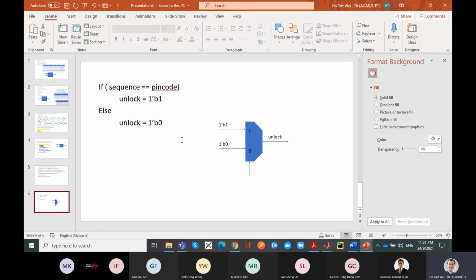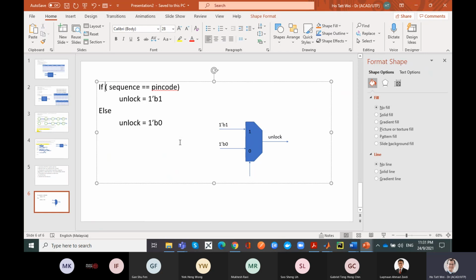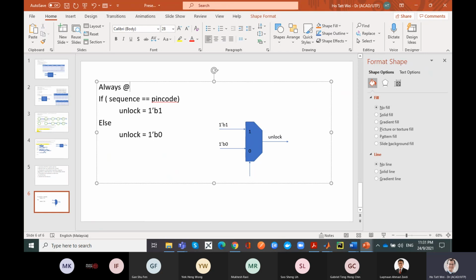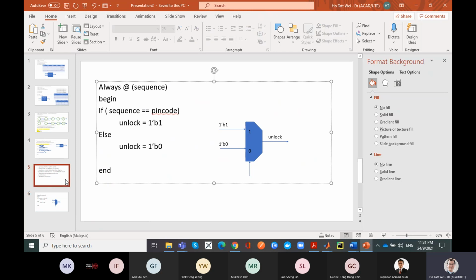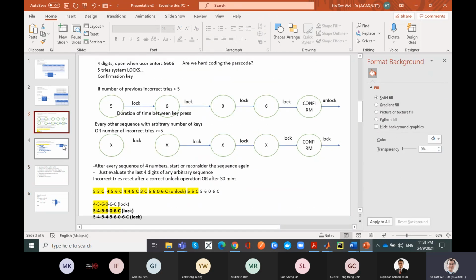And again, this one is very simple. And this is already very long code. So what I'm trying to say is, for these specific structures there is very specific Verilog code, and you can start to map it. And then we'll start to throw in D flip-flops, and you will just see that a state machine is actually very simple. It's not very difficult. It's more important how you define the states, the input and output situation, and all that.